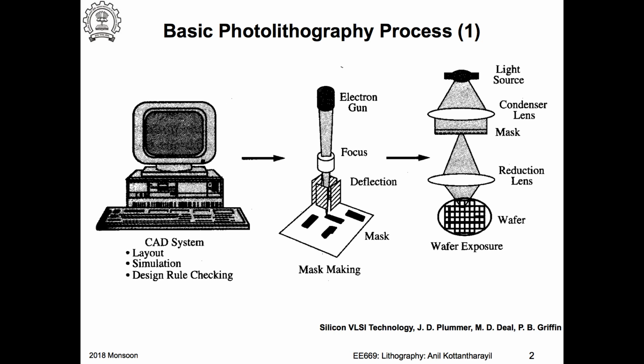The next thing is, of course, I can extract a circuit diagram from this layout, because I have a transistor, and this actually represents a transistor. Then see whether the eventual circuit would work. So you have all this design rule checking and simulation to see whether the IC or whatever circuits you're making would actually work.